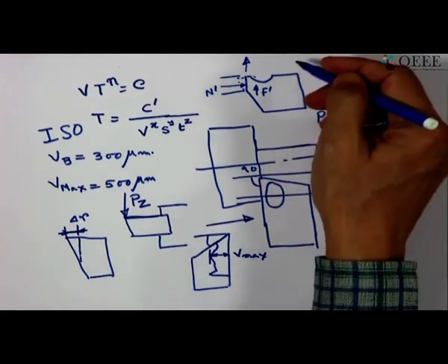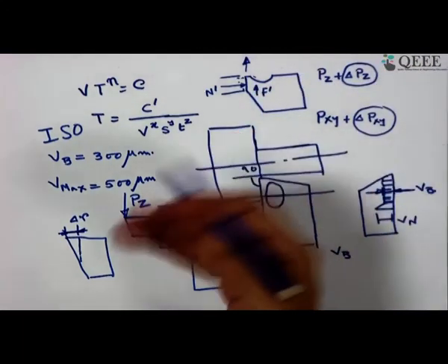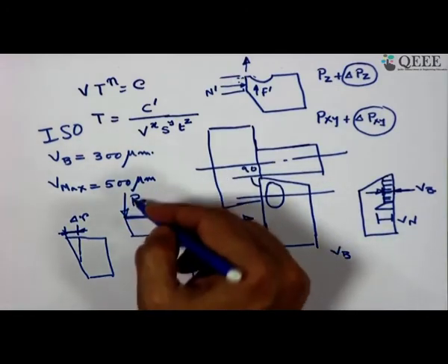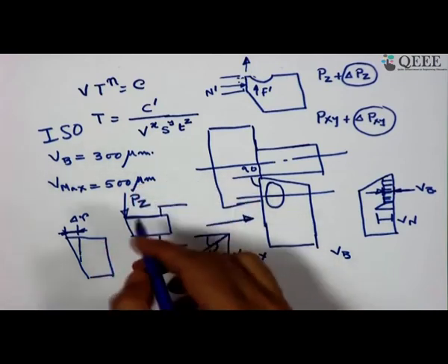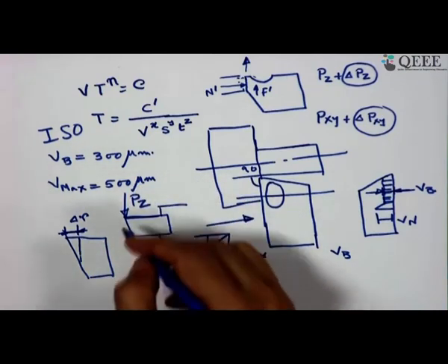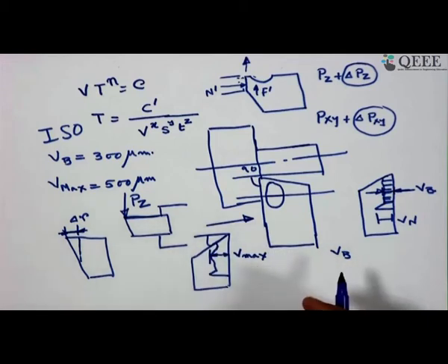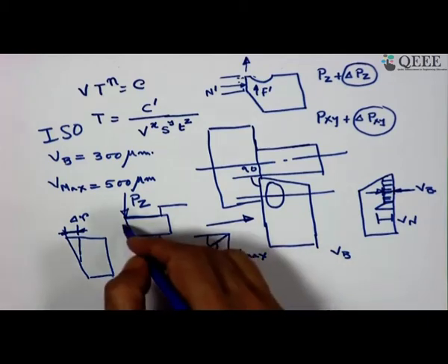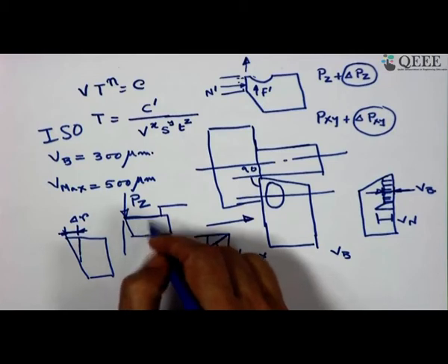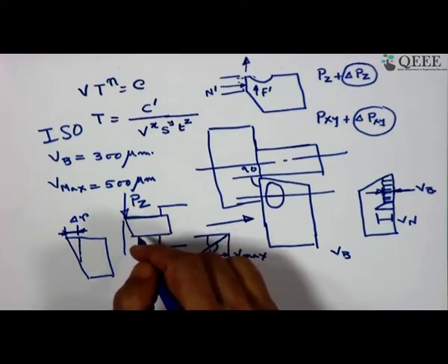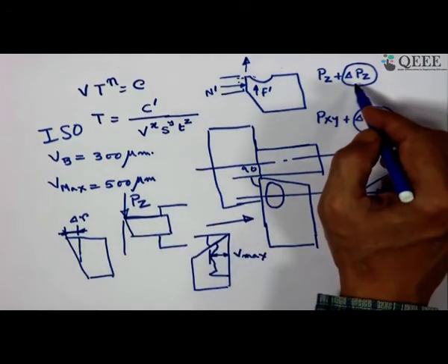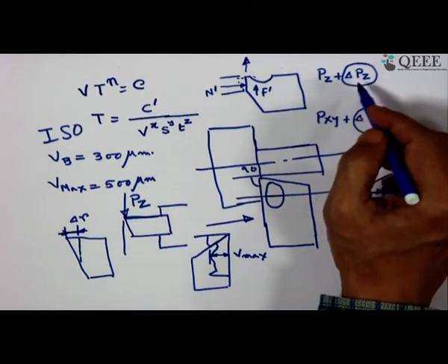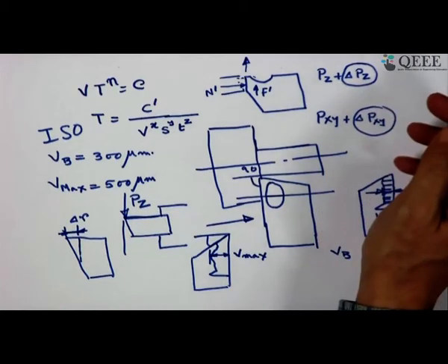The tool is exerting force, it is also at the receiving end, and that is the reaction, and as a result of reaction on this overhang, there is a chance of deflection of the tip of the tool. Of course, this depends upon the amount of overhang and the section modulus. Whatever may be the case, the fact remains that there will be little deflection, and with this add on delta z, the thing is not at all favorable, it is going in the unfavorable direction.